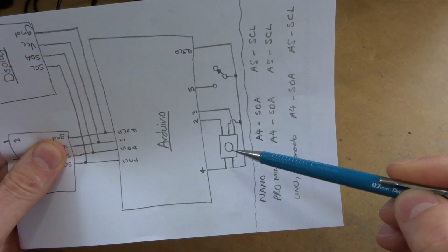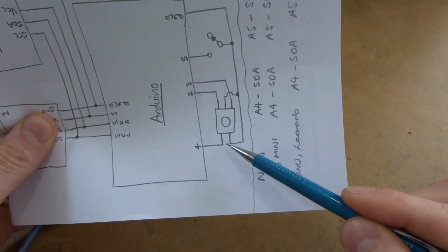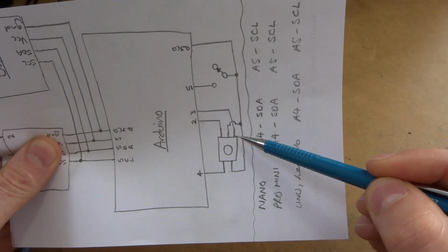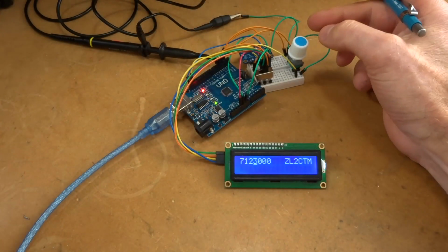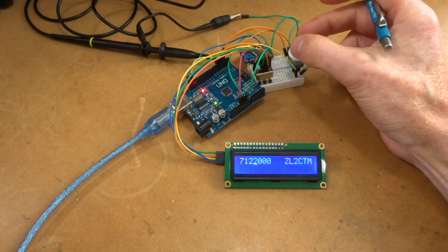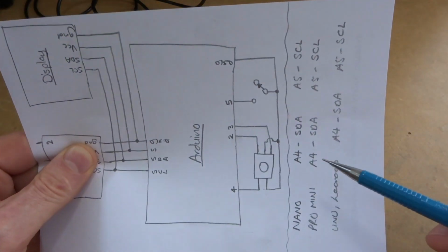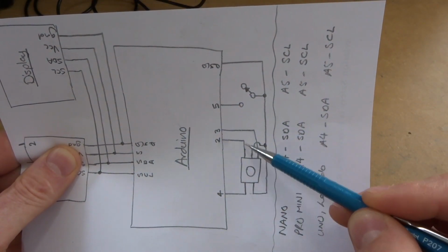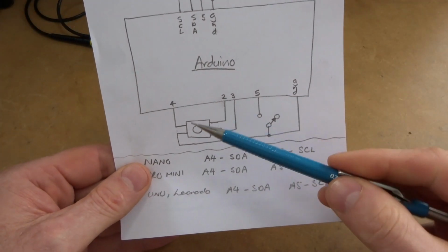You push that button down and these 2 get made, so they get closed. Up here, these 3 pins are basically the pulses, or the little short earths, that the rotary encoder sends out that need to be read and interpreted. The configuration for that is the center one goes to ground, and the other 2 go to the board. So that's what you see there.